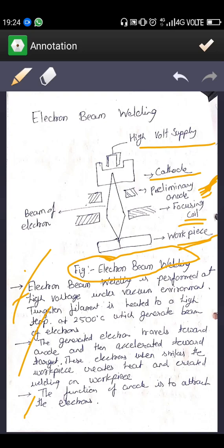In addition, electromagnetic lenses are used to focus the beam of electrons upon the target workpiece. This enables very deep penetration with a keyhole penetration mode at fast travel speed, providing low overall heat input. This hole is immediately filled by molten metal from the reservoir and forms the weld upon solidification.